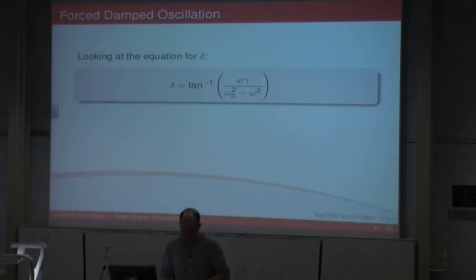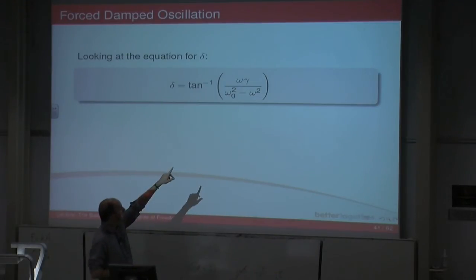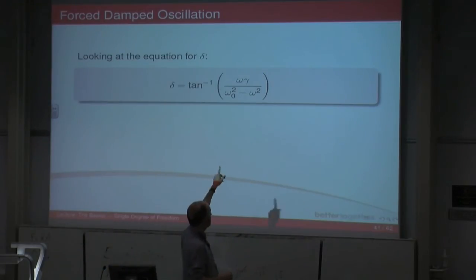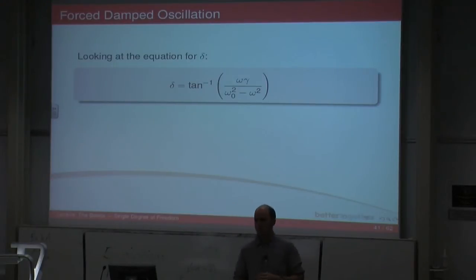What about for delta? Well, again, let's think about it intuitively. If omega is 0, so I'm not applying it with any great force, any great frequency, my period could be 100 years or whatever. I'm applying a force, but it's going to take 100 years for it to do an oscillation. Well, the omega term there drops to virtually 0, and notice that that's in the numerator.